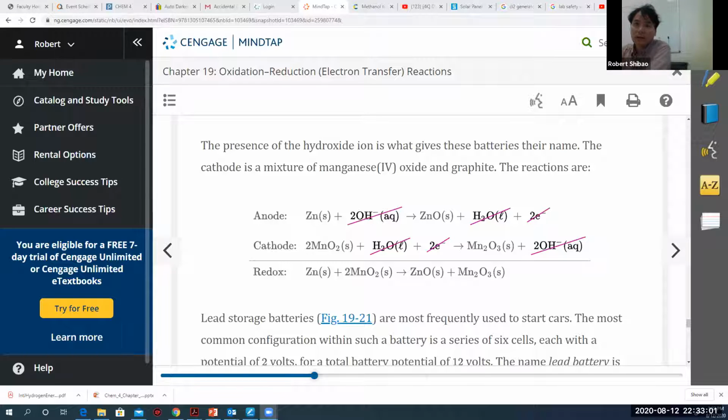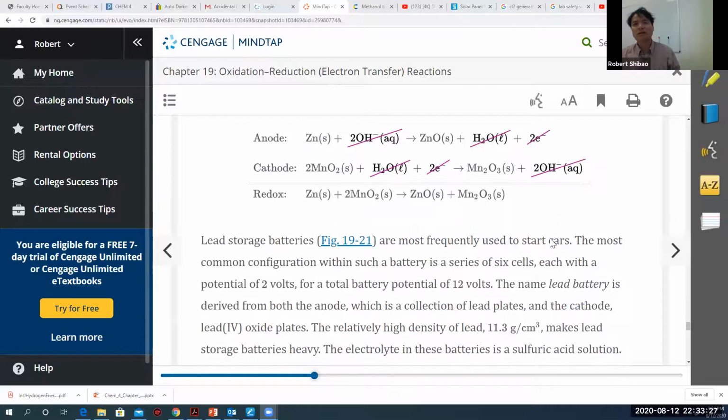Well, this brings up the strategy in these batteries. A lot of these batteries are all solids or pure liquids. If you have pure solids and pure liquids, then the concentration doesn't change. The concentration is fixed, so it gives you a stable voltage. Normally, if it's just a regular concentration, the voltage just starts to drop as the reaction takes place. And for a lot of things like an LED, you need 3 volts. If it goes below 3 volts, it's going to stop working, even though the battery still has life left in it. It just doesn't have enough voltage.